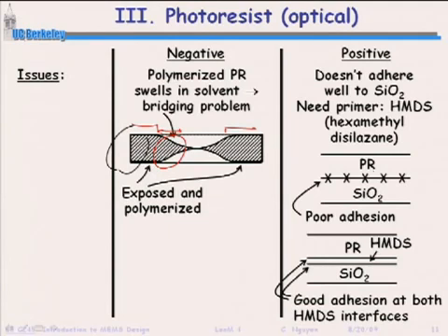Then you put the resist on top of that, and that helps it adhere to silicon dioxide, which is often the type of film that you're trying to etch. Okay, and so in the end, you get good adhesion. Positive resist works, so if you have a choice in which resist to use, positive, because it's going to have the better resolution.